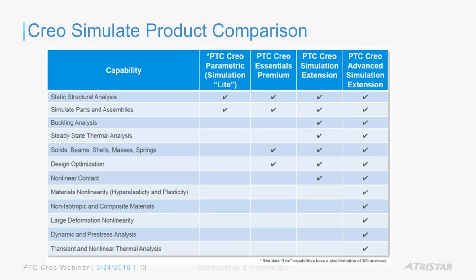I want to make sure the stress, deflection, or the model frequency, or even the temperature when I'm doing a thermal analysis, should be less than a certain value, and I can give a solution space, which is my design dimensions that you use for modeling your design in Creo, and you can use that solution space to achieve an optimum design.